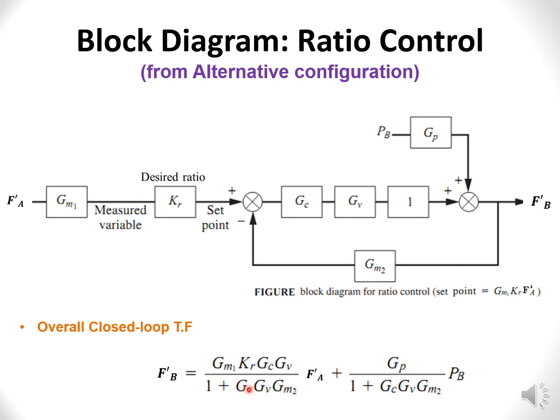And the bottom part is just the closed loop characteristic equation, which is 1 plus the open loop transfer function. This is the characteristic equation that will determine the tuning of GC, and determine the stability of the system here. It determines how it's going to behave, the mode of behavior, and so on, as we have seen before in the conventional studies. Similar methods can be used here.